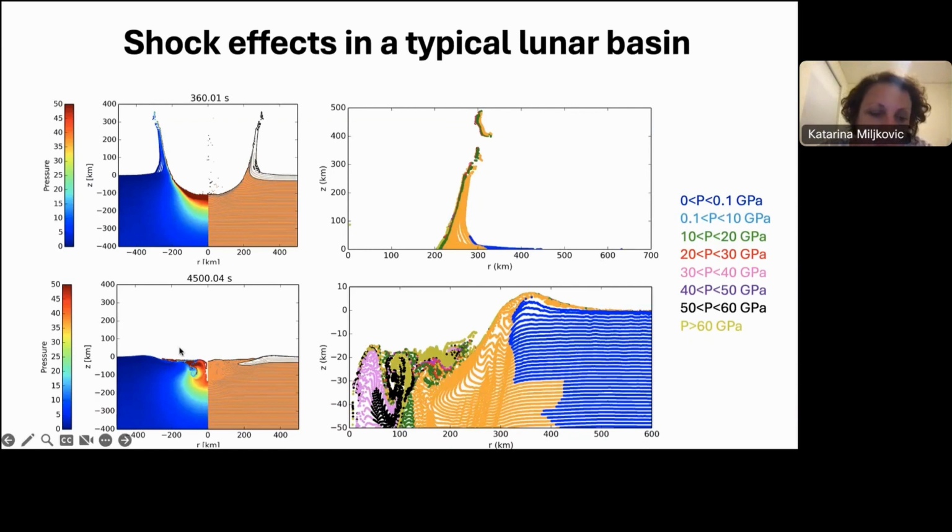left-hand side. So we're seeing quite significant peak pressures in the very melt pool, going over 30 GPa. And if we were to look at what's happening to the ejecta, then we have pressures that go up to maybe even 50 GPa, but not in the full volume of it. It goes above 10 GPa, but the orange one is the one that I don't have colored here in the color bar on the right-hand side, so I can't really explain.